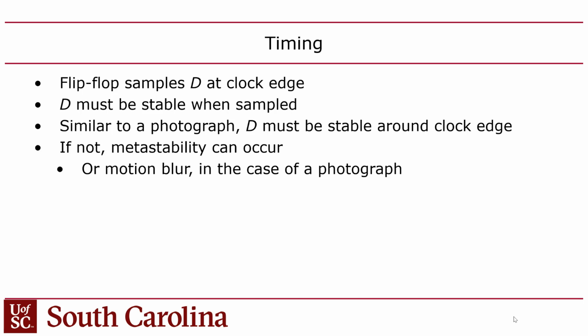But it turns out that's not true. That's not how they work in reality. Every flip-flop has a parameter called setup and hold time, meaning that you have to keep its input D stable before the clock edge for an amount of time called the setup time. And you also have to keep it stable after the clock edge, called the hold time.